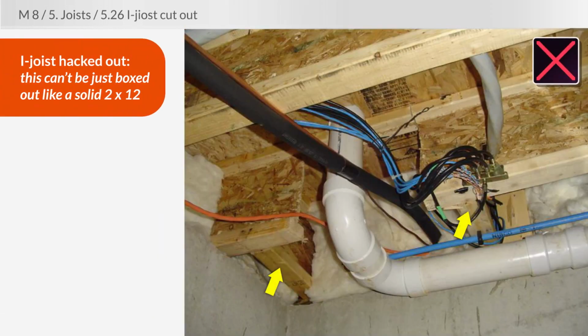This entire section of I-joist has just been hacked away. And then someone's tried to box it out with 2x4s. Well, you can't treat this like a solid 2x12. So you know what you have to do now. You have to recommend further evaluation by a licensed structural engineer.